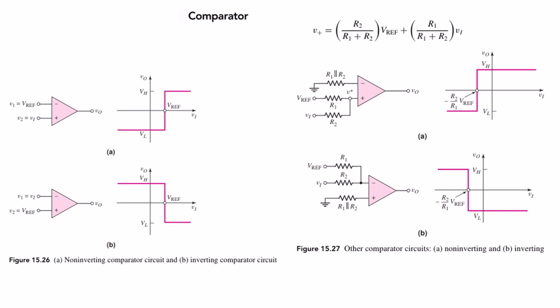If the input is higher than the V reference, then it will have the high voltage. Otherwise, the voltage will be low. So depending on the reference values, the output voltage will be high or low. So that is why this is being called an inverting circuit.